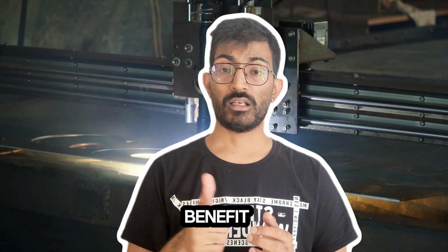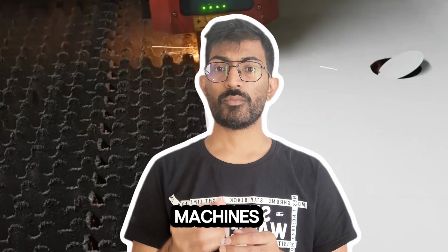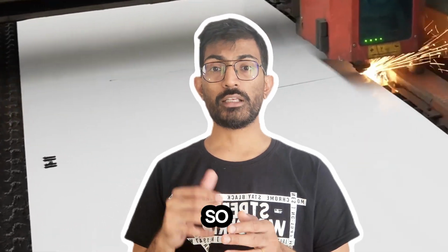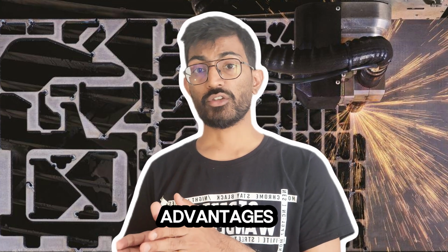Let's understand advantages and disadvantages of laser cutting. Laser cutters are very widely used in the industry. The first benefit is it is really quick. It cuts faster than any other methods that I've explained except the plasma arc. But with the new fiber machines, laser cutters are really quick. Also, you get really good efficiency because you get to nest the part before it actually comes to laser cutting. That means you can get a really good utilization of a sheet and have really good efficiency while you are cutting the sheet metal. These are the advantages of the laser cutters.